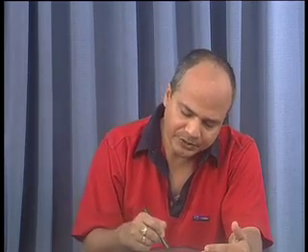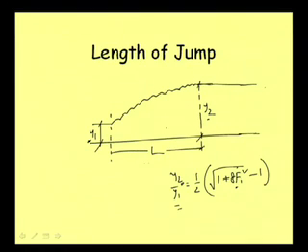By observing it carefully and having some idea about the y2 value, we need to decide where our actual jump is ending. Of course, practical observation is important, and to give guidance to the practical observation, these calculations may help you. Well, then knowing this y2, this length is basically L, and then we can have a relationship between the length of the jump and the height of the jump.